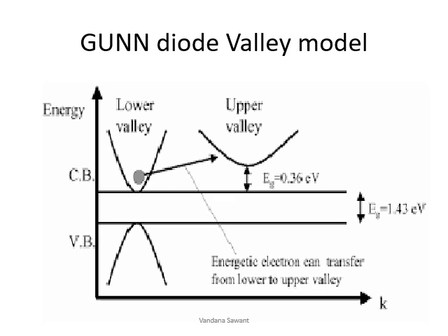Now, if you give a supply voltage V to the device, the electrons present in the valence band will absorb energy from the supply and their energy goes on increasing. As their energy increases, they jump to the conduction band. As they jump to the conduction band, their mobility goes on increasing. Mobility is directly proportional to conductivity, and conductivity is directly proportional to current. So the output current goes on increasing.